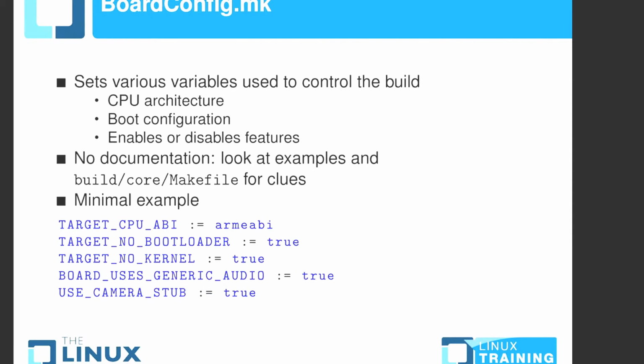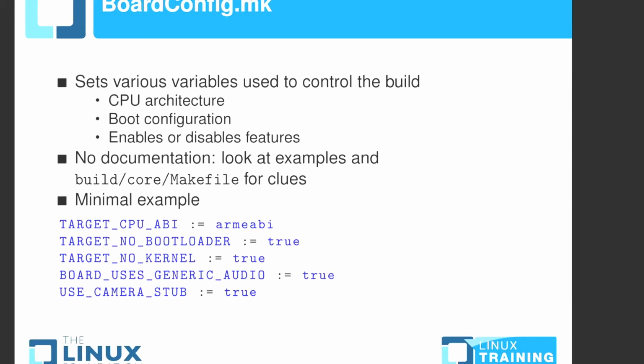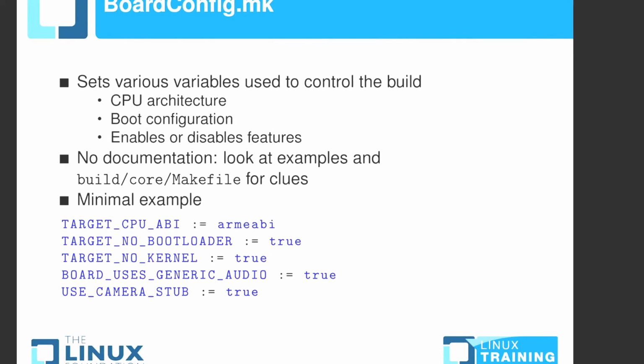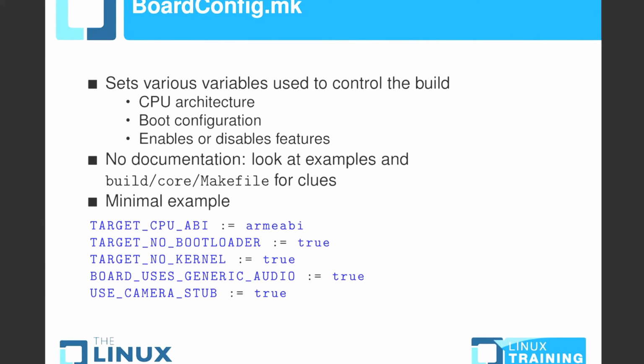Okay, next thing I need to tell you about, boardconfig.mk. Now, there's a lot of stuff that goes in here. I'm just going to cover, again, a few basic things just to get us up and running. Basically, we can use it to define what processor we have, what memory we're going to be using, and what flash images we're going to be using.